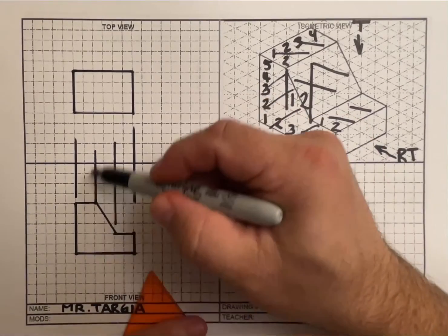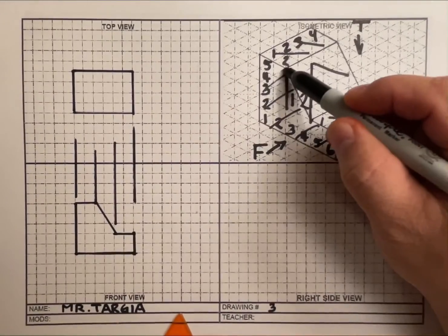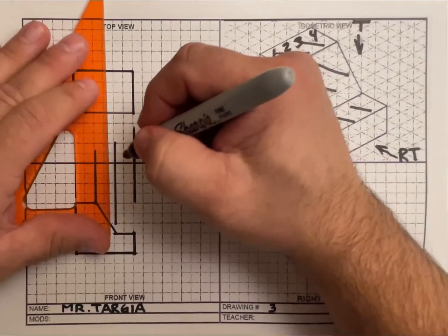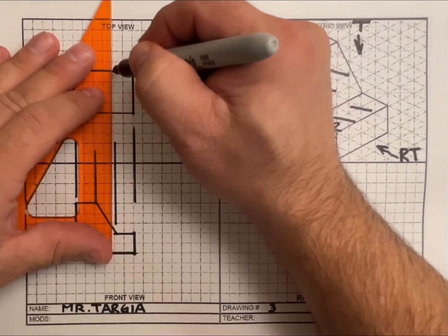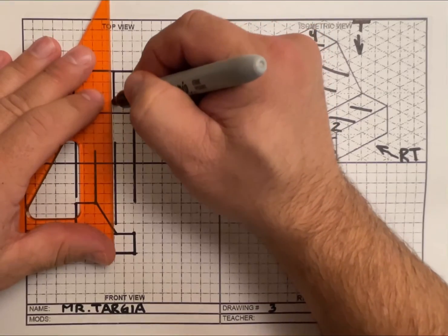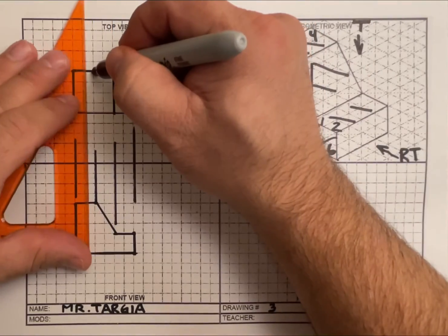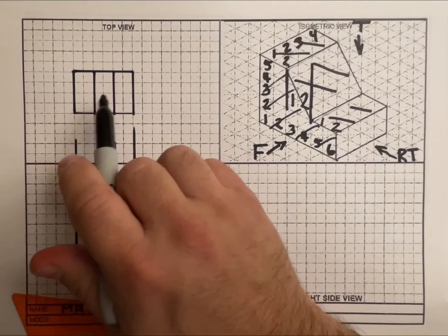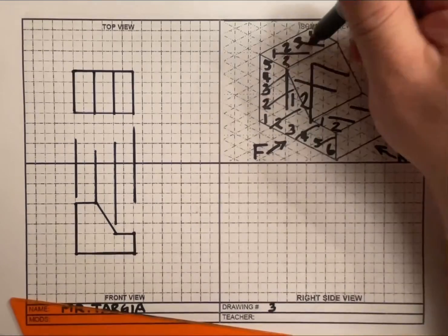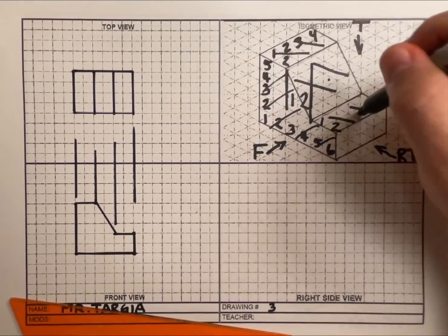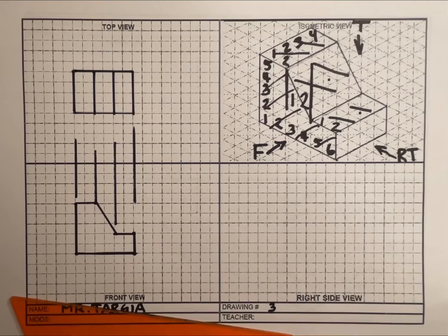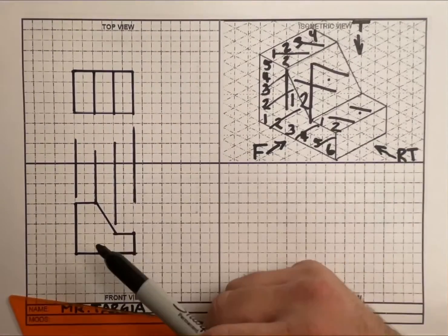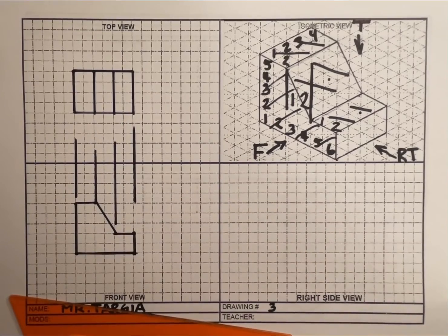Now these projection lines here are going to tell me where this line is and where this line is. So I'll simply follow my projection line, take my straight edge, line it up, and put it in place. That's 1 and 2. So there's 3 equal parts on the top view, because this part, this one, and this third one are all equal, okay? Even though it's slanted, when you're looking straight down, you can't tell that it's slanted. Therefore, it looks flat when you're up above.